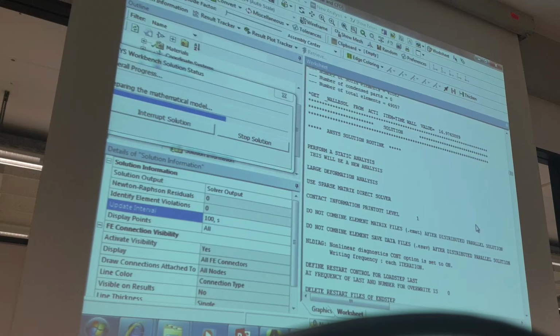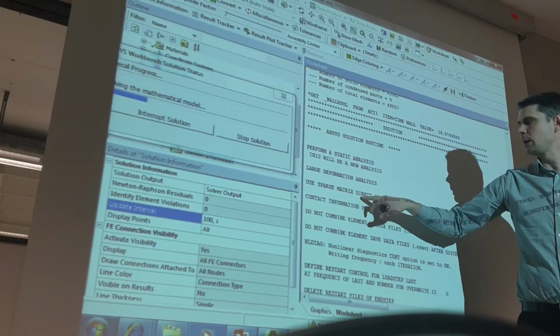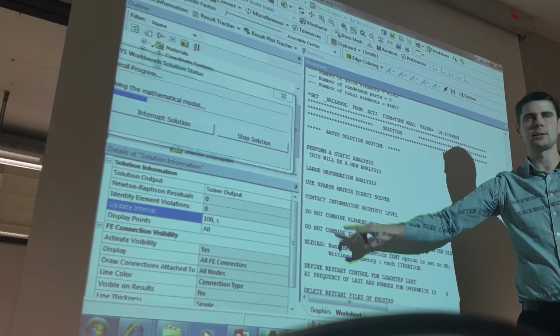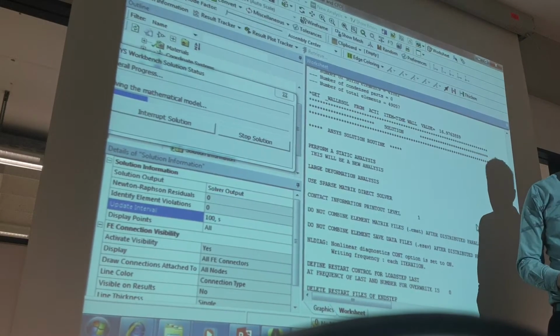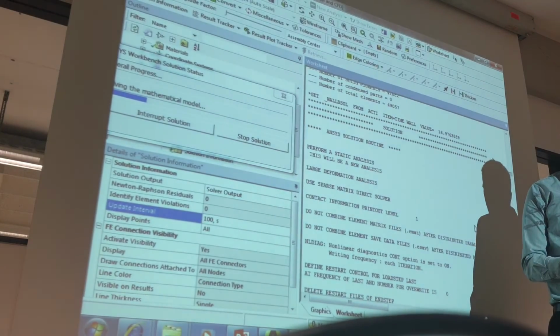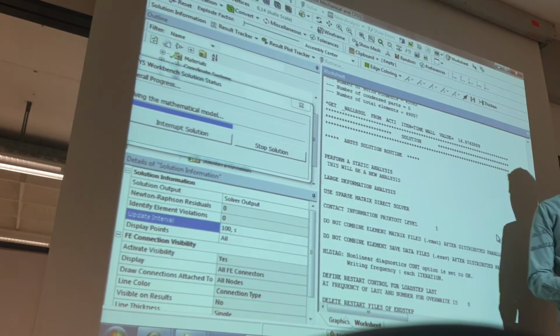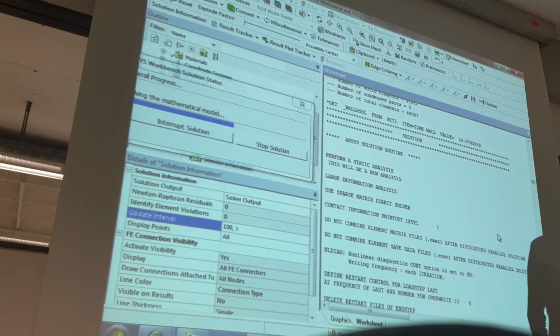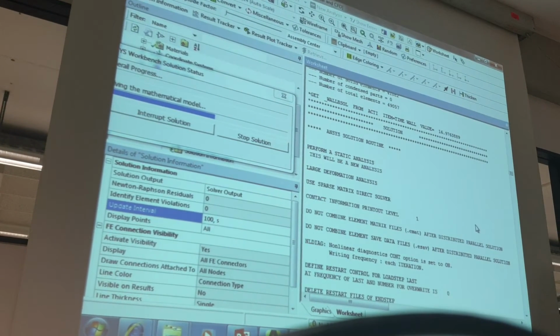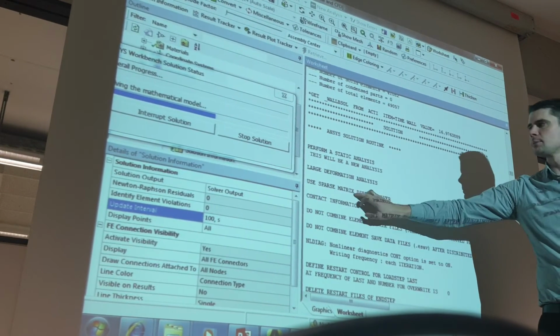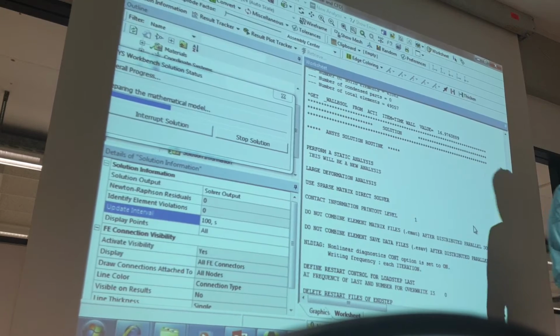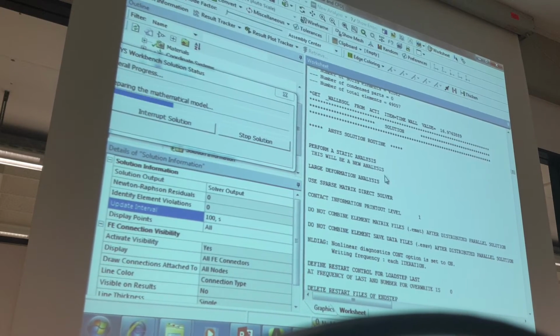Yes, and you see here, for example, the program uses the sparse matrix direct solver. Sparse means that we avoid multiplication with zero elements. It's like a modification of the Gauss method that uses this. We don't need to do zero multiplication. So our matrix has many zero elements, and then a special direct solver tries to solve it.